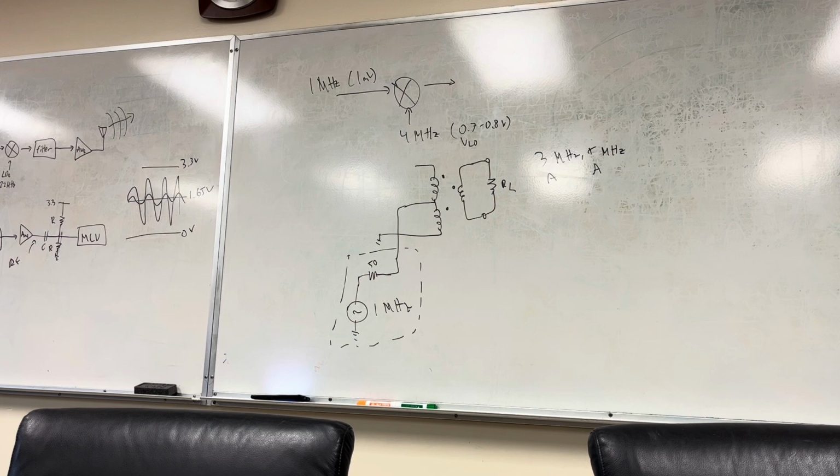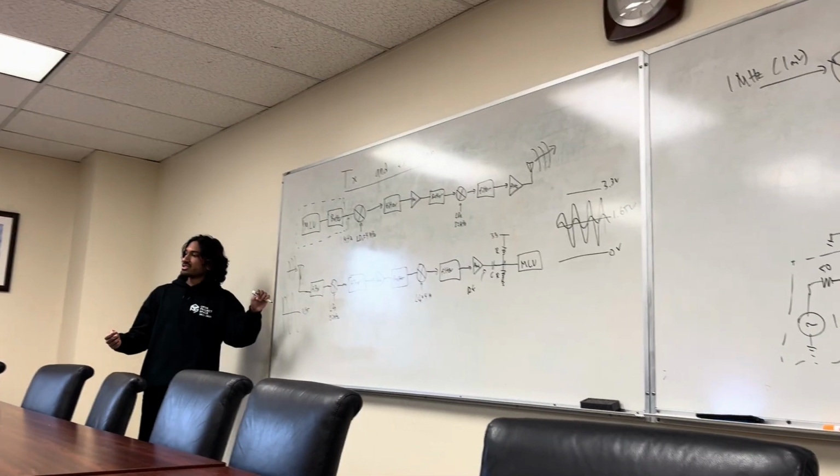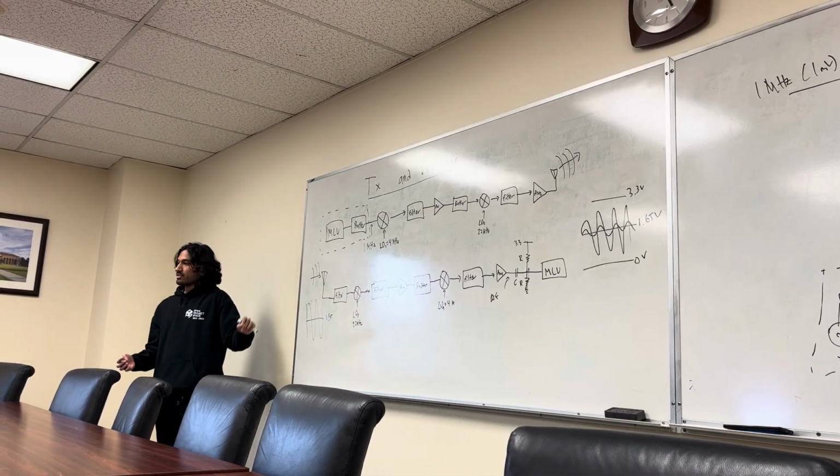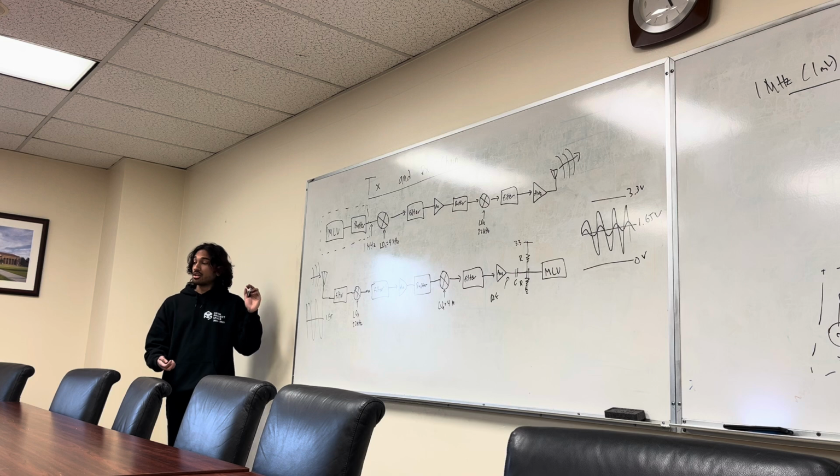And this is important because modern day mixers, the way we view them is from the LO port, it is nonlinear. From the IF port, it is linear. If this signal is too strong at the IF port, we can no longer view it as a linear network, which means that we're now going to get more harmonic distortion. All right, and these are kind of complicated words. You'll probably see these later, but generally, if the system is linear, you put in one frequency, you'll get one frequency out. The more nonlinear it is, the stronger the harmonics of it will be.